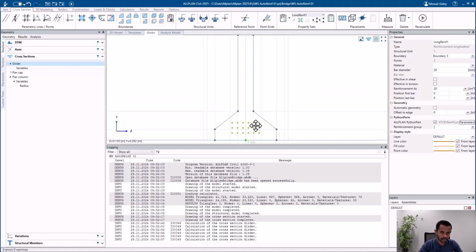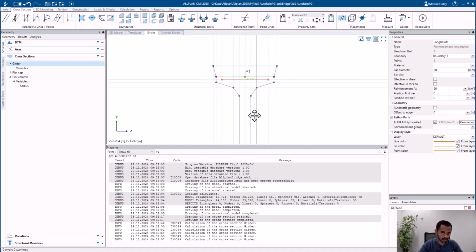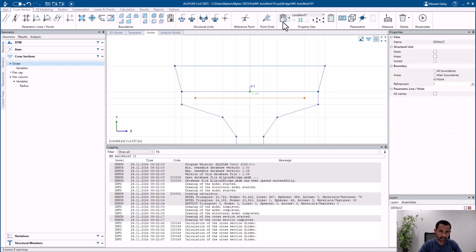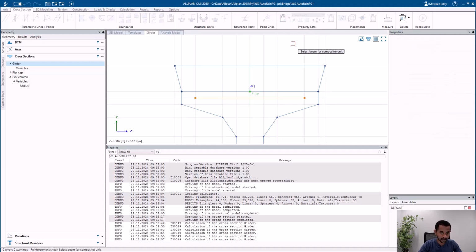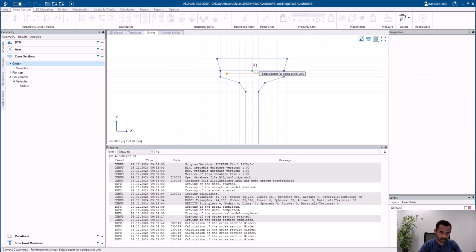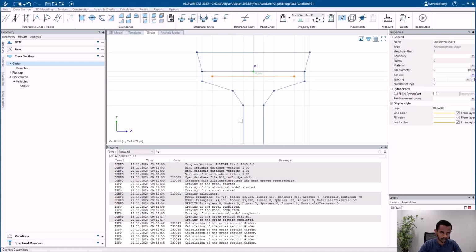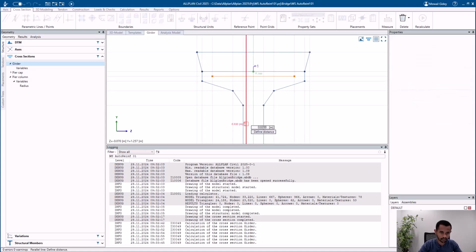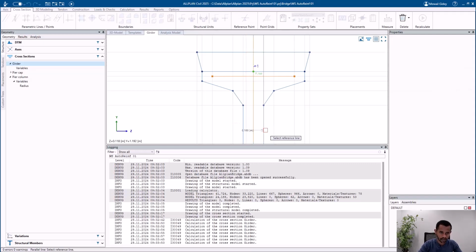And the same goes also for the transversal bars, so we could also add another transversal bars. Let's even group them actually, so it would make sense. So I'm gonna say group 1 like there, and add a transversal one or a shear one, and I'm gonna define it also there. Here I'm gonna use an offset from here. Let's add an offset 0.03, and the same also here 0.03.